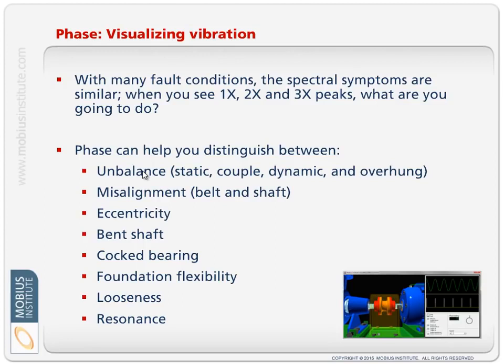But do you know the most common reason why balance jobs fail? Because the machine wasn't out of balance in the first place. Someone sees high vibration, oops, that's unbalance. Even if it's a high 1x peak, it's unbalance. And so the machine has to be stopped, person gets in there, safety issues, all this sort of work, and then they find out it's not out of balance, it's misaligned or something else. So, phase helps us understand that.